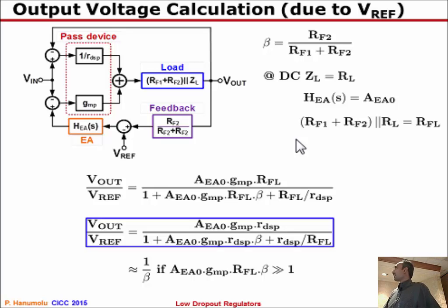And in the denominator, if you remove this feed-forward path, there are no more loops. So this is 1. Typically, for like 90% of the things that we are interested in, it's always going to look like 1 plus, there are 2 loops. One loop is this, EA0, GMP, or RFL, this loop. That term is shown here.